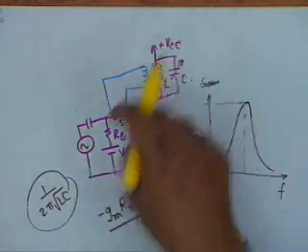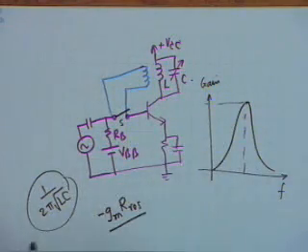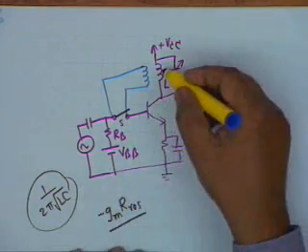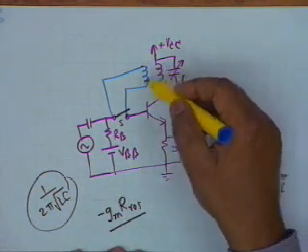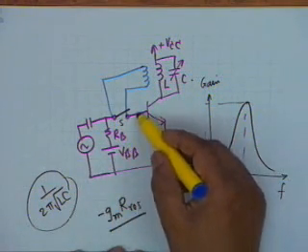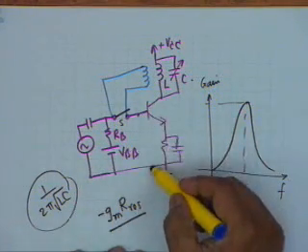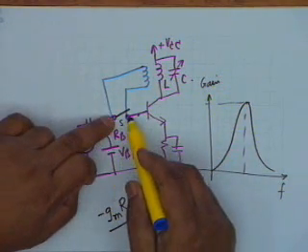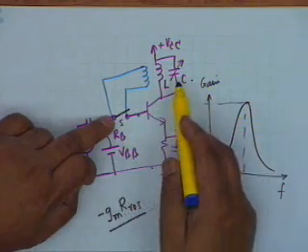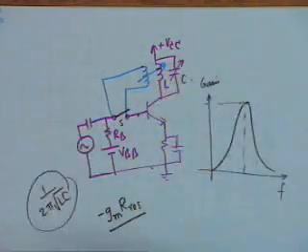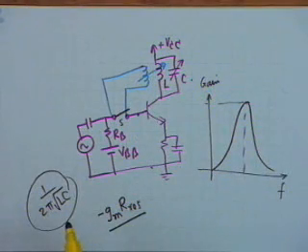We can so orient the winding direction such that a part of the output is fed back to the input. You see, the actual signal at the input between the transistor base and ground shall be the input signal plus the signal that is fed back from the output because of the magnetic coupling between these two inductors.